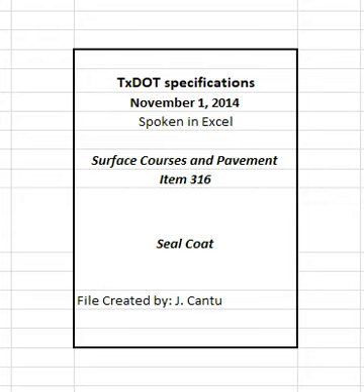4.1 General. Comply with the seal coat season as shown on the plans. Asphalt and aggregate rates shown on the plans are for estimating purposes only. Adjust the rates for existing conditions as directed.